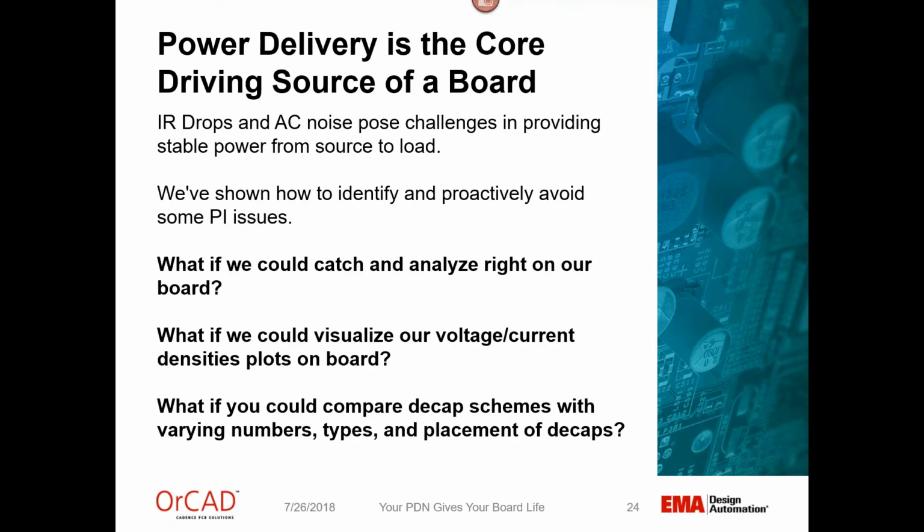Before we step into our demo, let's go over again what we've covered so far. Our total noise budget has to tackle both the voltage drops, the IR drops, and the AC noise that we see. We've shown you some tips and ways to look out for our IR drops, as well as how we can use decoupling capacitors to reduce impedance in our operating range and to reduce power plane resonance.